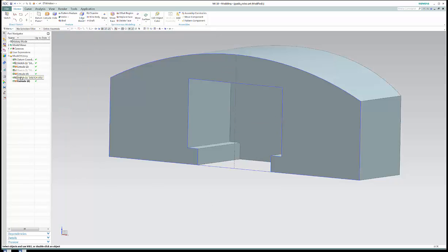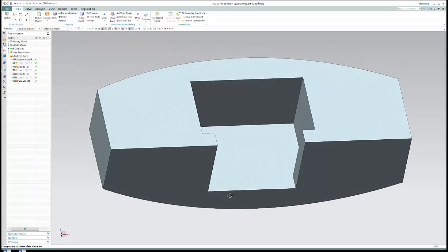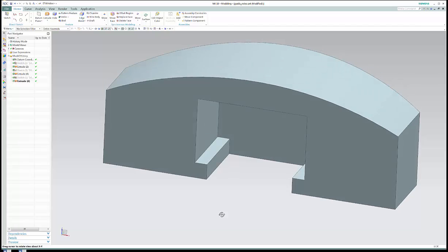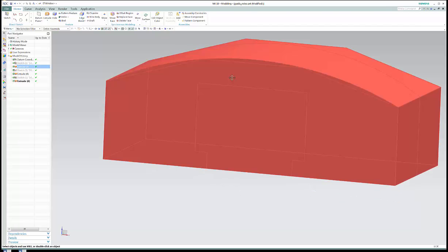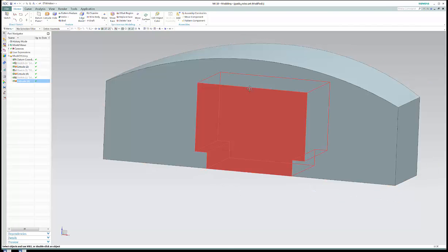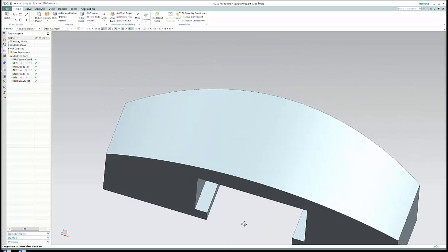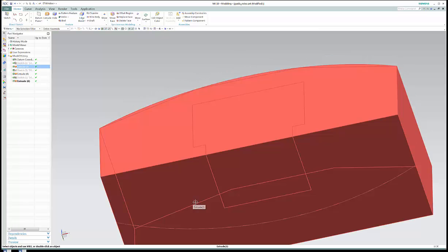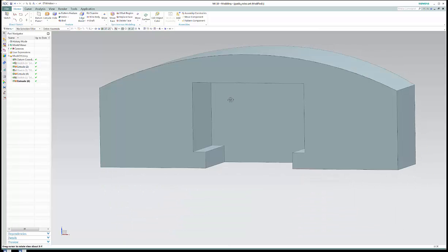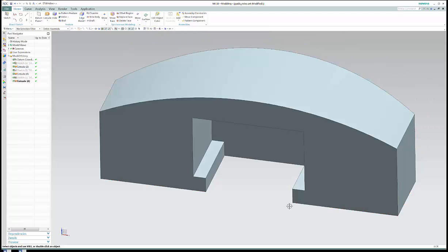Now we can right click on that sketch and hide that, and it won't show up, and we can right click on this sketch one and hide it, and all we're seeing is the cutouts. Okay, now if you didn't have much material between this edge and the top, then you probably put it on the wrong flat surface. You probably put it on this one, but that's okay. You don't have to redo this. You can just go back in and flip your radii around and you'd still be okay.